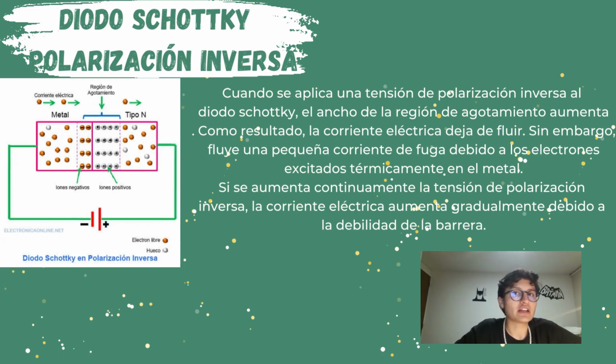As a result, electrical current stops flowing. However, a small leakage current flows through the electrons in the metal. If the bias voltage is continuously increased in reverse, the electrical current gradually increases due to the lowering of the barrier.